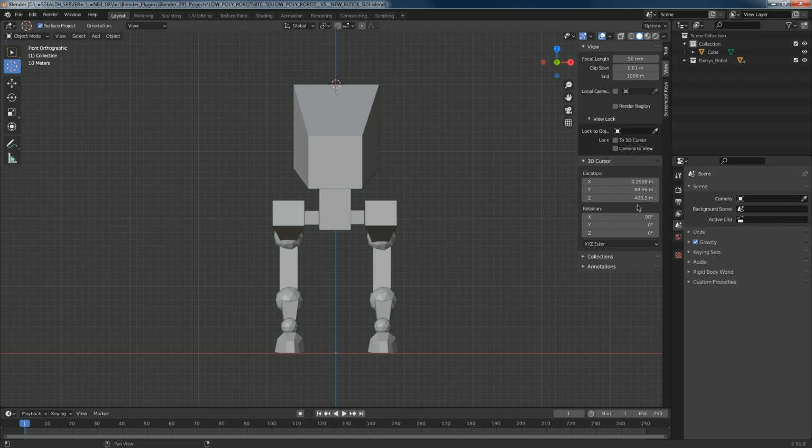So it's quite significant, but if you're up around 300 meters, it's probably okay. With this robot, because of the size of the spheres that I was using, just to avoid getting any errors, I found if I scaled it up to about 400 meters, I was not getting any errors. Now, the model that Boo342 had created, his was about 250, I believe. So just make sure that you're around 250 to 300 meters in height from the world origin point. You'll be okay when you're exporting your model.